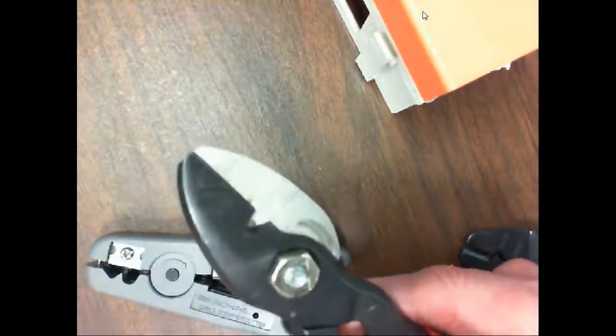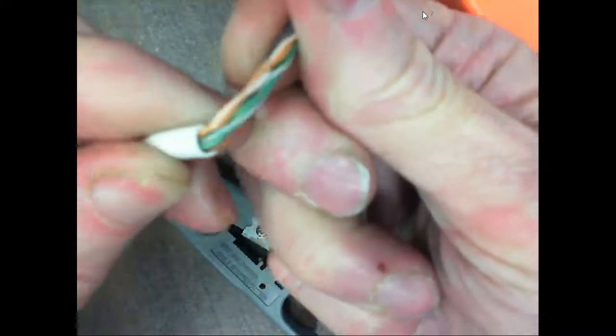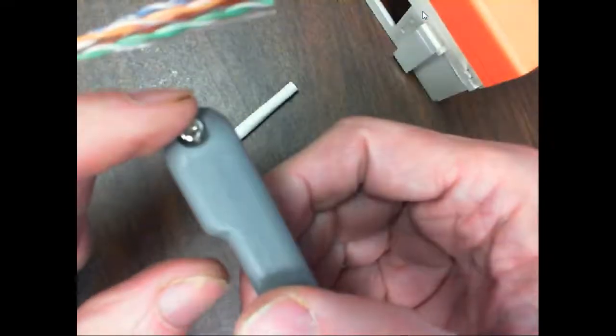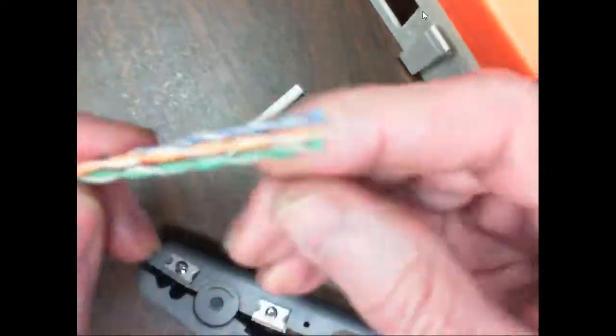I've seen cable cutters that was actually hydraulic. So all we need to do is strip this jacket off. So we come in here, lay this down in here, and all we have to do is spin it. And what we want to do is make sure that it don't nick the wires. So if I see that it nicked the wires, then that means I need to come in and do what? Adjust the blades out a little bit. Everybody okay? Does that make sense?